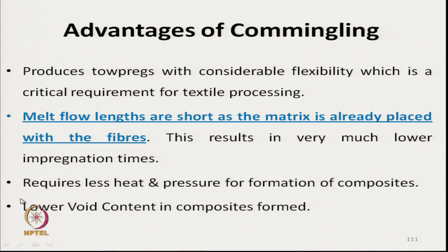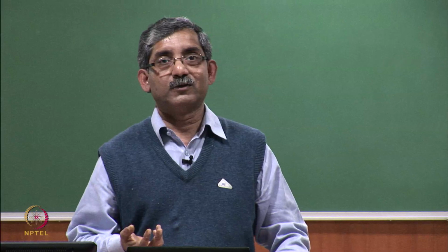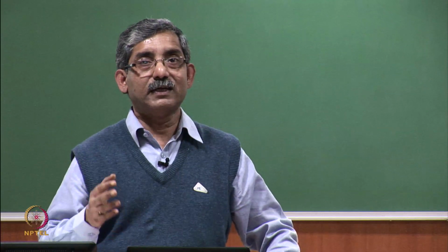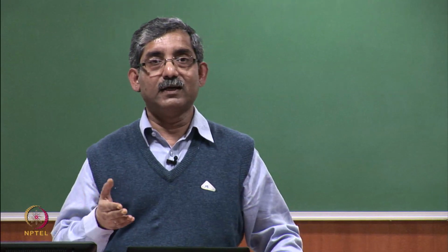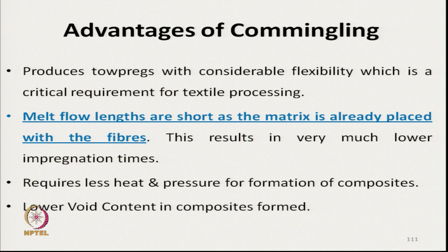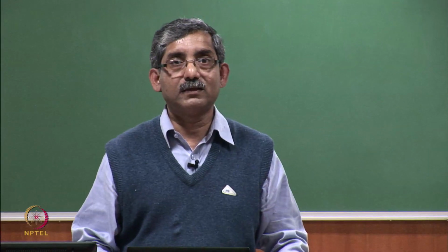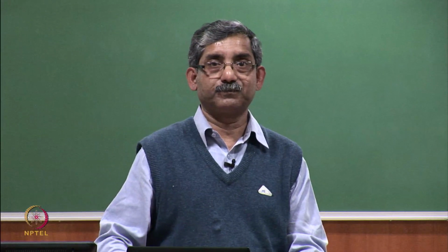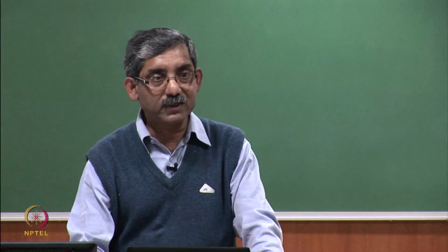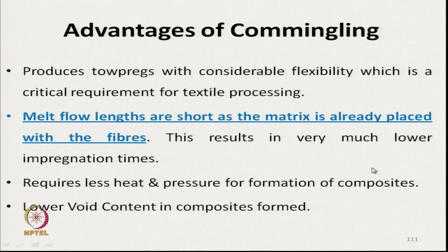As we do not need very low viscosity, less heat is required. Only melting is enough, and as the flow length is less, the pressure requirement for composite formation is also less. So, lower void content is there due to the matrix component already present within the structure.